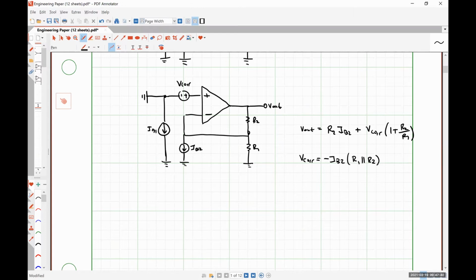The problem is that since our corrective voltage depends on IB2, and since this current depends largely on process and temperature, because it's representative of a base current in a BJT, we have no guarantee that our circuit is always going to operate at the exact same temperature and things like that. So that voltage may shift over time, or the necessary voltage may shift over time throughout the operation of the circuit, which means we're not always going to correct.